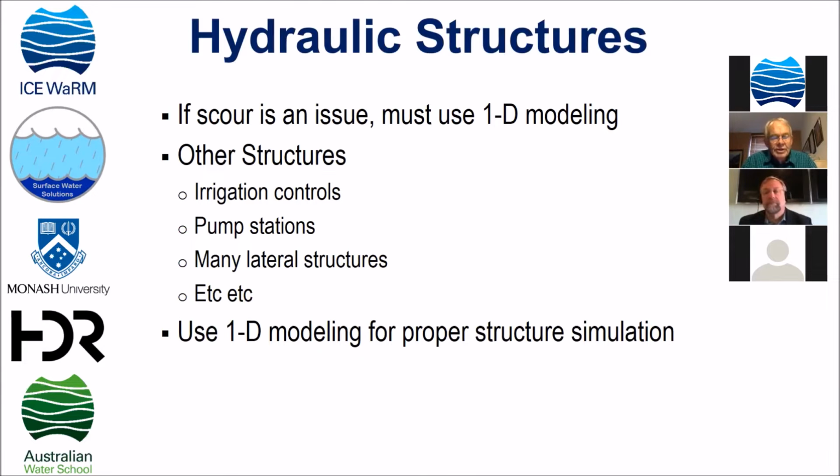And these rating curves, of course, can in themselves model structures where a 1D model of the structure has been used to generate a rating curve, which can then be put into the 2D model. That's as far as I want to go, just to emphasize that we need 1D models where we have significant structures, because the modeling components within the 2D model are currently not particularly extensive.